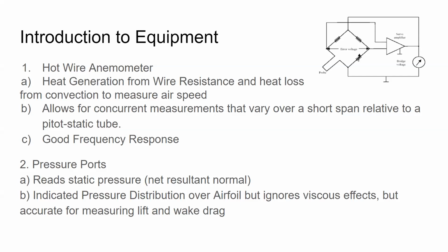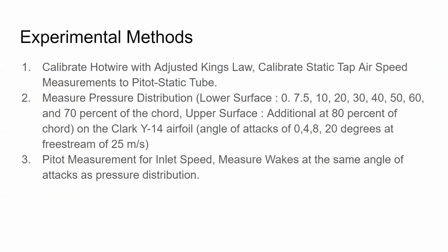Well, if you want to calculate drag through this method, you'll be ignoring viscous effects, which are important for streamlined objects. Pressure distribution would be very important for a high angle of attack airfoil, or a blunt object like a sphere or cylinder, but in this case, it won't really suffice for measurable drag distribution.